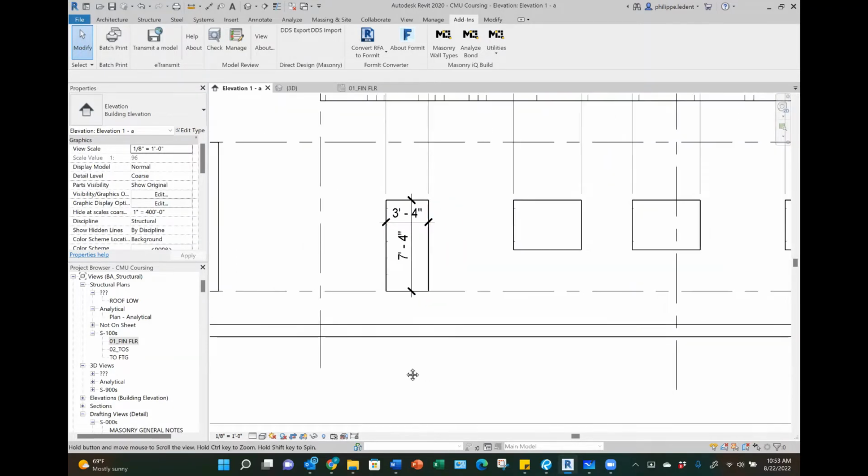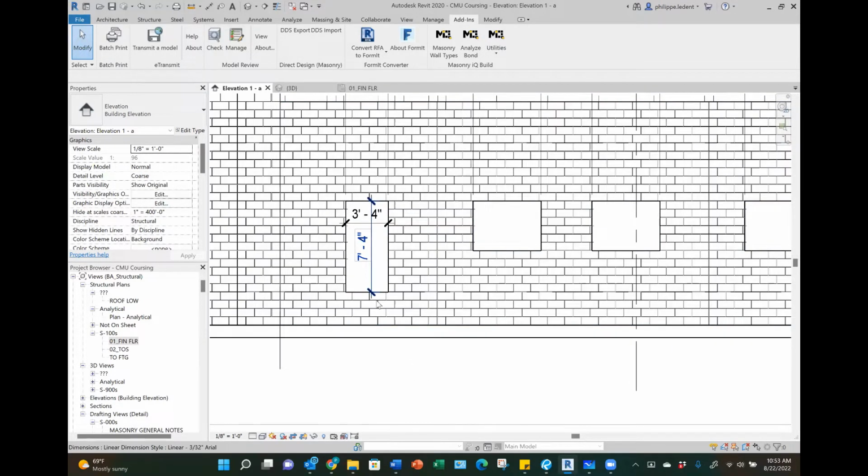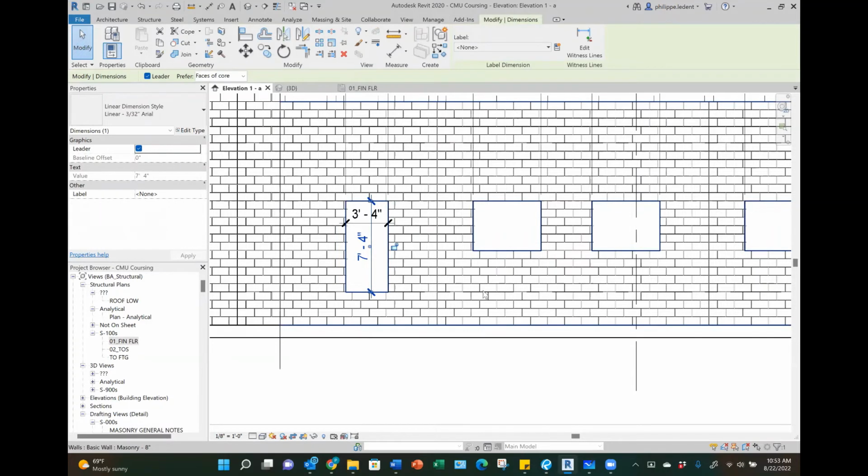Other issues that I have here: typically with masonry walls, we're commonly going to have a 7-foot door, so that's 84 inches for our door height, and we can get a 4-inch head on that door frame. And with that, we have a nice modular layout. Our entire rough opening here will equal 11 blocks, if you count them, which makes that 7-foot door height, which again is our 7-foot door plus a 4-inch head on that door.